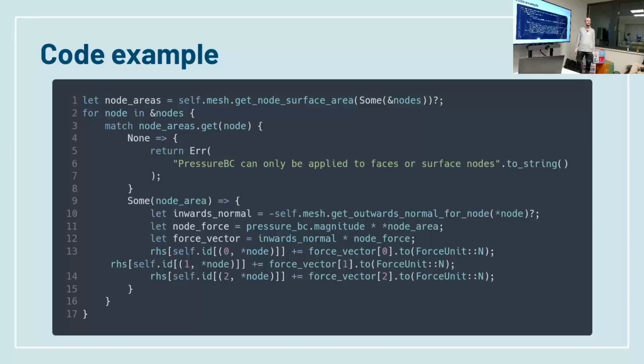Awesome stuff. And by the way, all FEM solvers on the market just work on pure floats. So it's up to the user to find out if the unit system he is using is actually consistent and what the numbers he's getting out actually mean unit-wise. That's also something I think is not a good design feature.